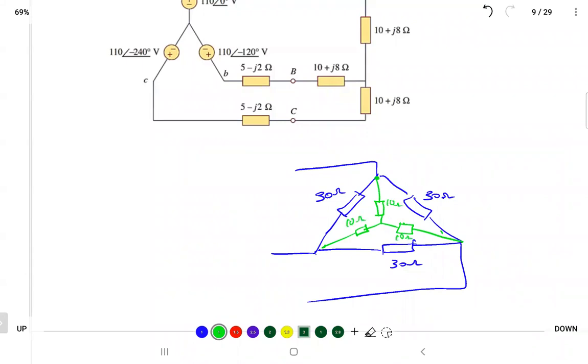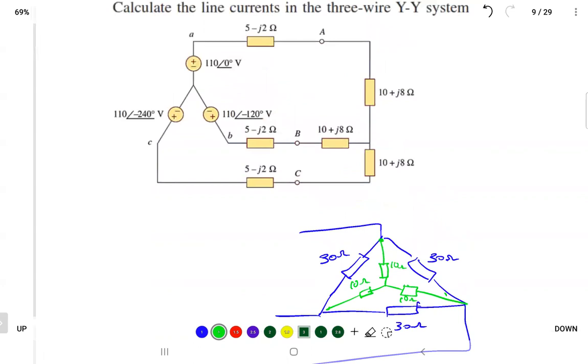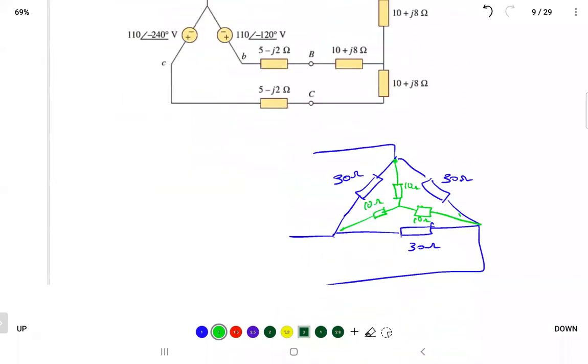And you go ahead and continue using the same method as when we solved the Y connected load. Find the equivalent single-phase circuit and just do it the same way that we did. So no problem. If you have delta, just convert it to Y. If you read the textbook, there are other methods you can read if you like, but I prefer to have just one method and stick to it and understand it well. So that's the way it's solved.